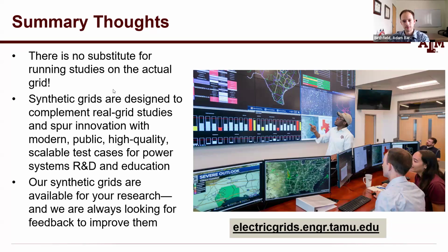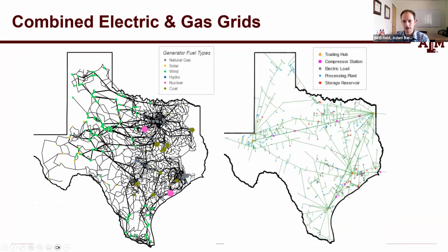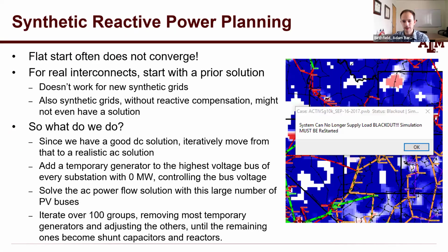If I understand the question correctly, we're talking about mainly this slide right here. The approach that we're using is to run these as PV buses in the interim. As PV buses, they're going to be in the Newton-Raphson power flow, they're going to have unlimited reactive power, or at least a large range of reactive power capability, and they're going to be regulating the voltage magnitude.